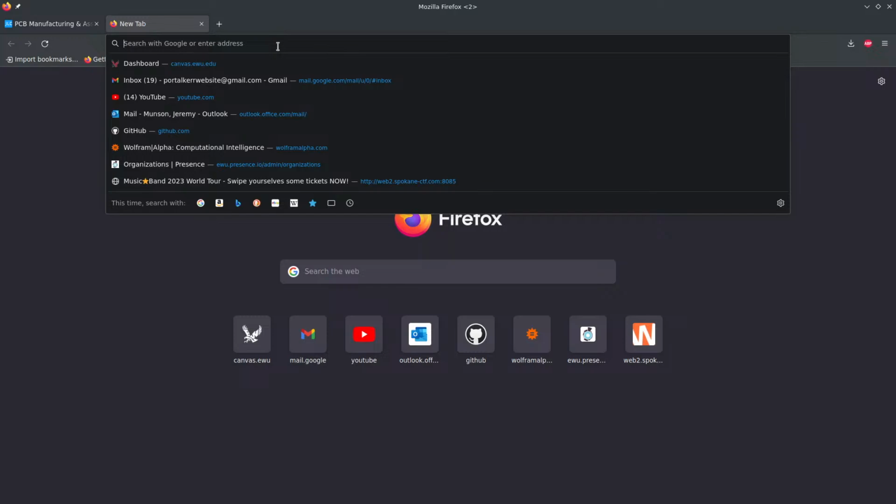And you can look up, there's a lot of information. A lot of people use it for hobby things, so it makes it really easy to find information about stepper motors. Every time you give it a step pulse, it will advance by a certain amount. And it happens to be by default on these, with no microstepping, I'll get into that, 200 pulses per one full revolution. So if you set up your timer to output a pulse every certain time, and then you run it for 200 overflows, or you have an ISR that counts the overflow and reset 200 times, and then you stop it, then you'll have done a full rotation.